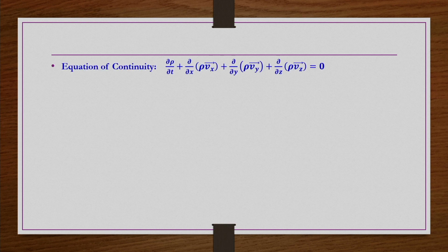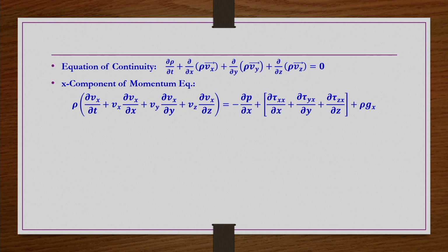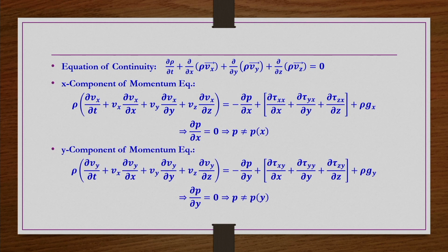The constraints, simplification of the continuity equation, and simplification of the momentum equation, whether it is the x component or y component, whichever component, are the same. We get the same outcome from simplifying the momentum equation, because the constraints are the same, only the rheology of the fluid has changed. That comes into the picture only after we have the shear stress expression.